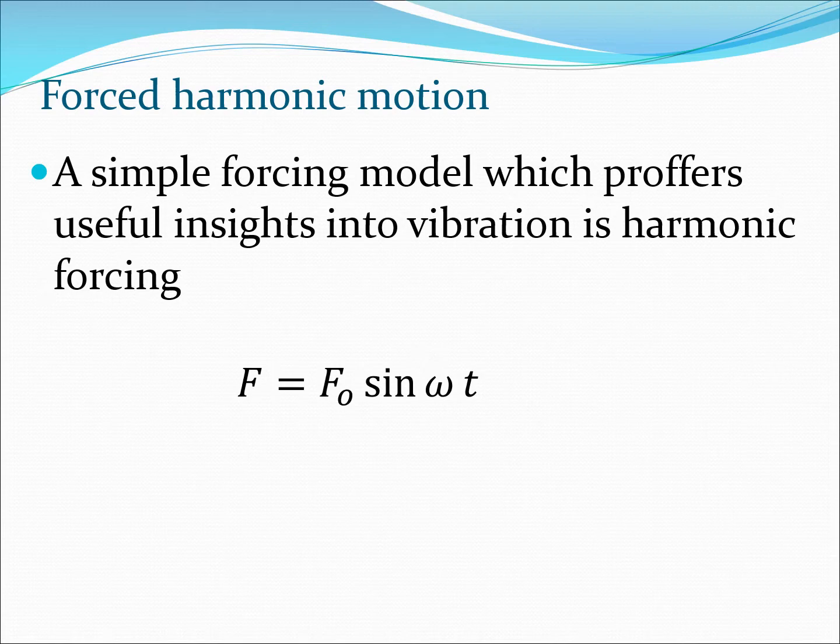So a simple forcing model which lets us get a lot of good insights into vibration is the simple model given here, that is F equals F naught, which is a constant, into sine of the forcing frequency omega into time. Remember that this forcing frequency is different from the natural frequency of the system. That is why we are not putting the subscript n here. That's the big difference.